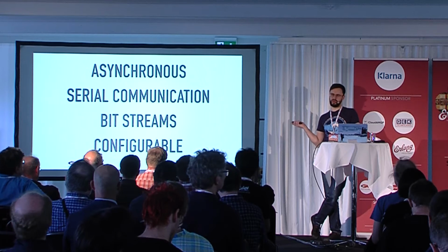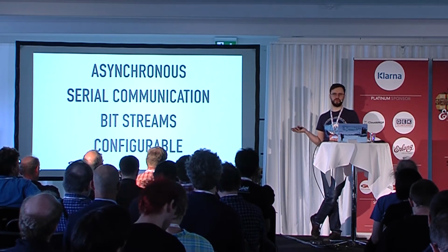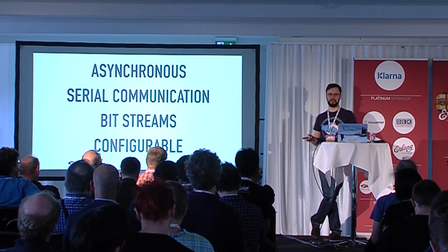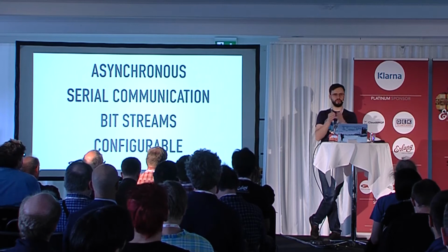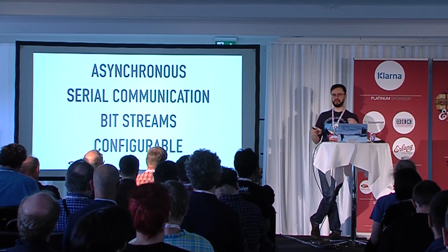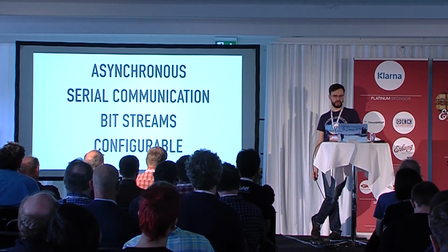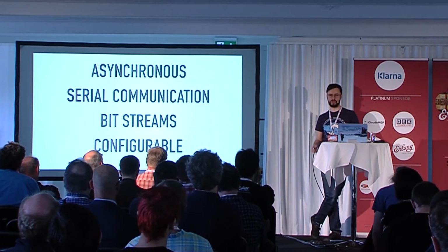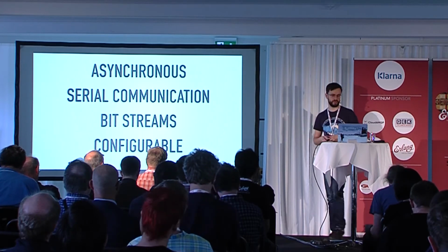Normally when you talk to UART devices, it's a text-based protocol most of the time. You send a command, like a string with some codes or a word and some parameters, and then you listen and the device sends something back, for example. So it's a very simple one, but it's much more high level than GPIO because it's not about controlling pins, ones and zeros. You actually have text, for example.